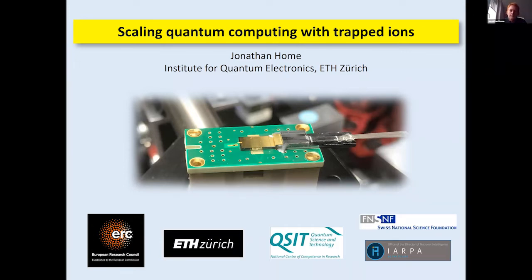And in particular, here's just a view of that from the sort of conceptual angle, if you like. Here's actually a chip. This chip has gold electrodes on it. And above this chip, about 50 microns above, we can trap individual ions. But the new feature of that chip is not so much the ion trapping itself, though that's something which these surface traps are sort of 15 years old or so. And here you see the electrical wiring.